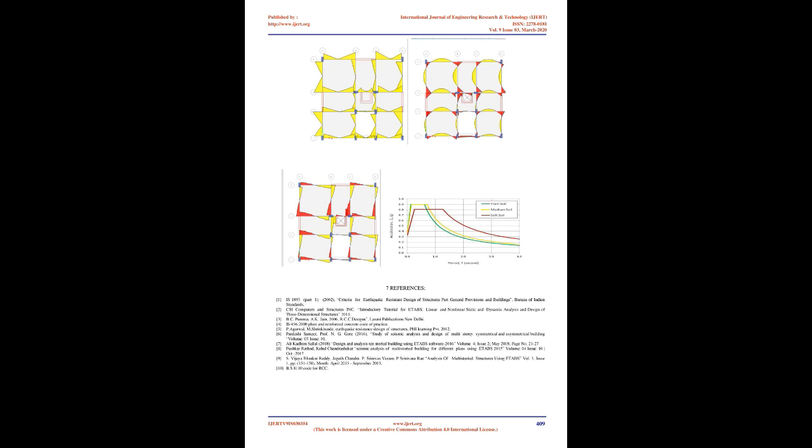From the above tables design, it is observed that shear force values in IS code are higher than values in BS code until story 7, and for stories 8, 9 and 10 values in BS code are higher than values in IS code. From the above tables design, it is observed that for all stories rebar percentage values in BS code are lower than values in IS code. From the above tables design, it is observed that shear force and reinforcement values in IS code are lower than values in BS code. Images show.